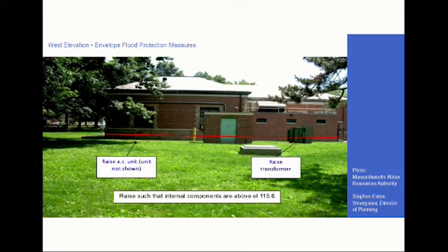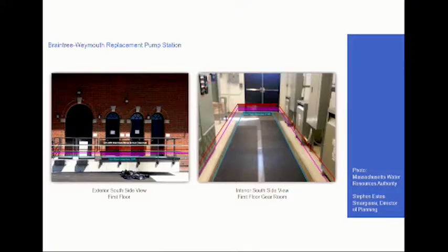And then finally, this is a very practical matter when you're looking at a utility site. Let's say that you go onto your utility and you're going to be putting in some new pumps or some new electrical boxes or retrofitting the air conditioner or something like that. You can look at what the sea level rise projections show the 100-year to be on that site, maybe raise the air conditioner, raise the utilities that serve it, and then project those further inside the building. And you can see where it doesn't take much to raise these electrical boxes, pumps, other things inside the building so that they are protective. So if you're replacing them anyway, you could look at maybe raising them up and considering a future condition.